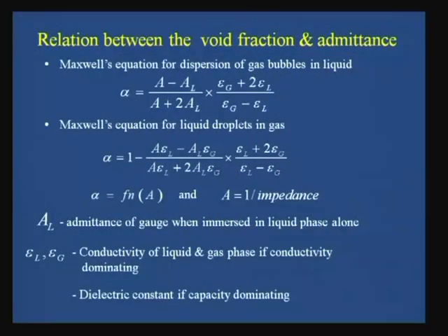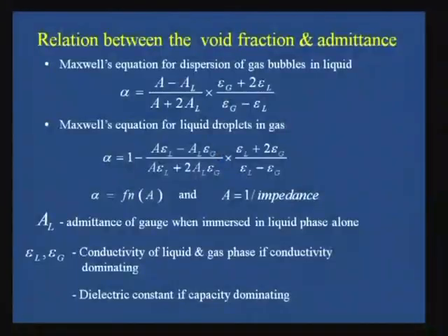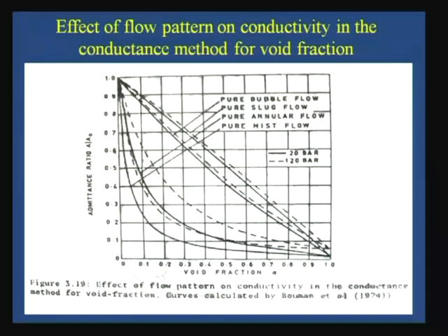So, the thing is we find that even for dispersed flow, when the dispersing and the continuous medium are interchanged, we have different relationships, and definitely totally different relationships will be there when we are having dispersed flow and when we are having separated flow. Even for separated flow, the same relationship cannot apply for stratified cases and annular cases. Okay. Now, this particular figure is going to show you the effect of flow pattern on conductivity.